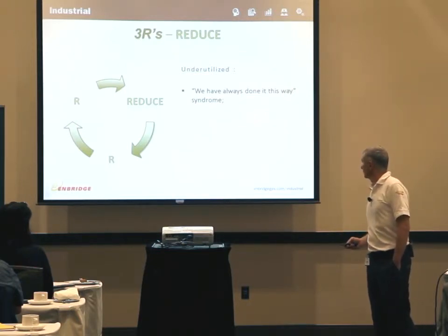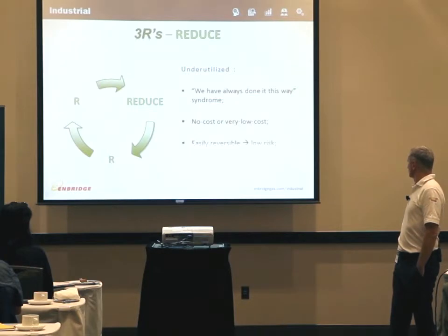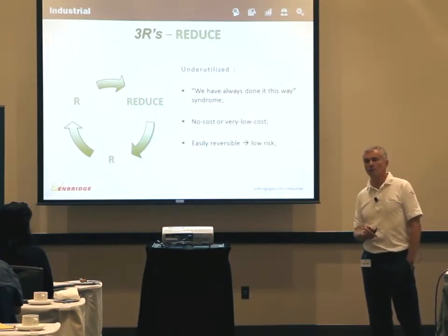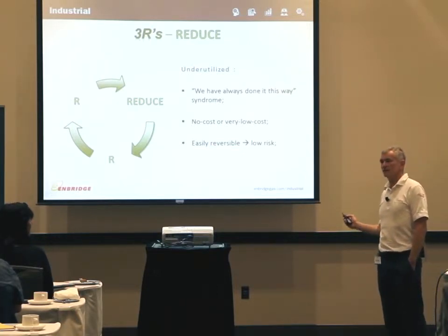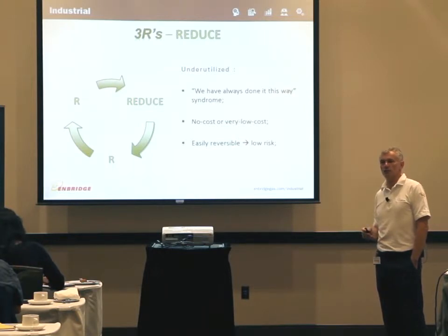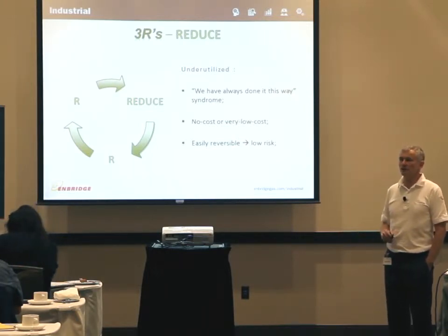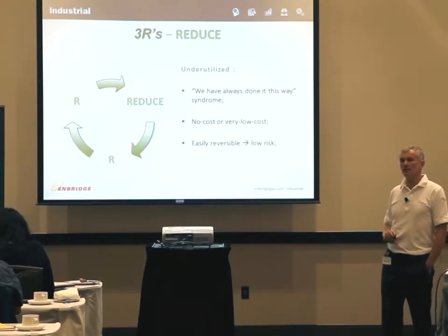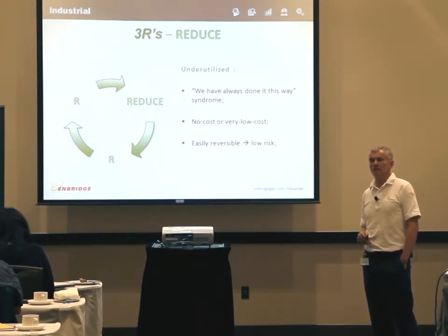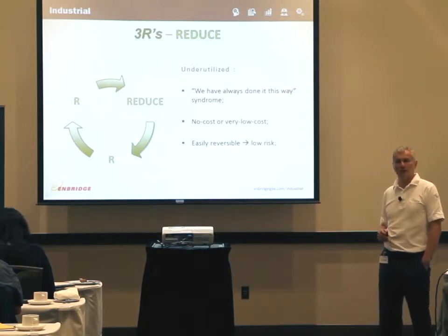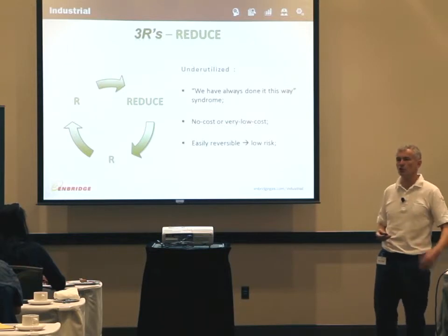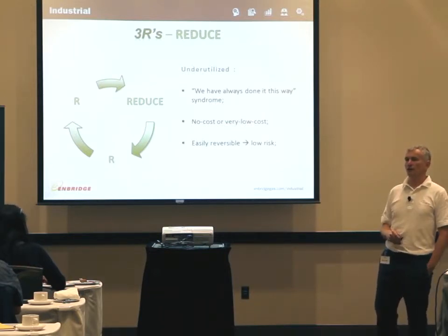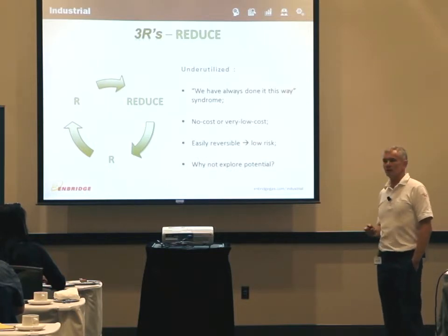Because ultimately, those are no cost or very low cost implementations. What does it take to change the set point? Right? And they're easily reversible. Everybody talks about the risk to production. Well, if the set point of 350 degrees F is not right, put it back to 360 degrees F an hour later. It's okay. You didn't risk that much. And we can help you estimate what the potential upside is, so you don't go blind. You don't just say, I'm going to change it for the sake of changing. No, I'm going to change it because the potential for savings is this much. So why not explore that potential?